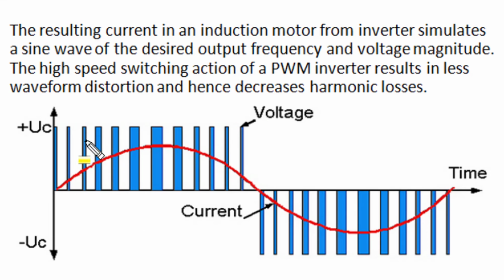The switching of IGBT switches is controlled in such a manner that for the middle pulses the width is taken relatively larger, and for the side pulses short width pulses are used, and together when synthesized they form an almost sinusoidal current distribution for the output supply. And a microcontroller controls switching of the IGBT switches by PWM technique in such a way that we get the desired output frequency and voltage magnitude.